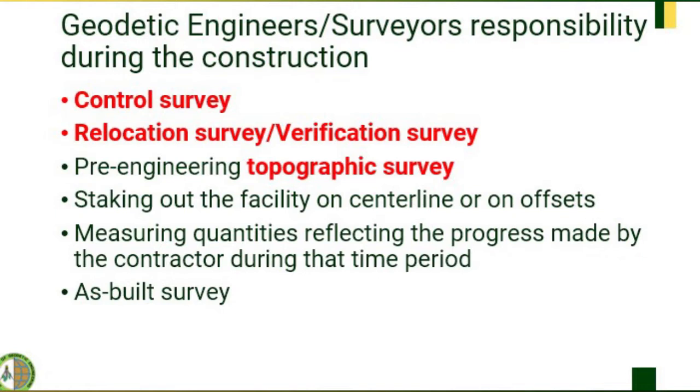Then from the design, these works are then laid out from the same control points used in the original engineering surveys. So the same with conducting cadastral survey or different kinds of survey. First and foremost is we need to establish controls, no? Because this will serve as our reference for laying out points based on the design, diba?